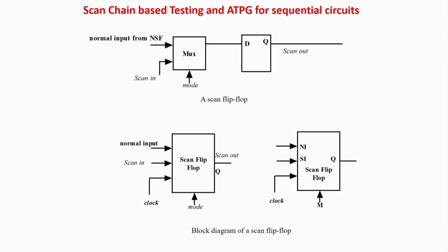And one beauty is, in the case of fault model, you might argue that I am not going for functional test of the circuit, so they cite a quality compromise in the level of test. But in the case of scan chain based testing, the complexity has been lowered, but there is no quality compromise in test, because we are not compromising in any kind of fault model, nor in the number of test patterns. But what is the slight compromise? We slightly increase the area overhead. So that is very well accepted. So scan chain you can think of as a big thumbs up when you are going for testing of sequential circuits.